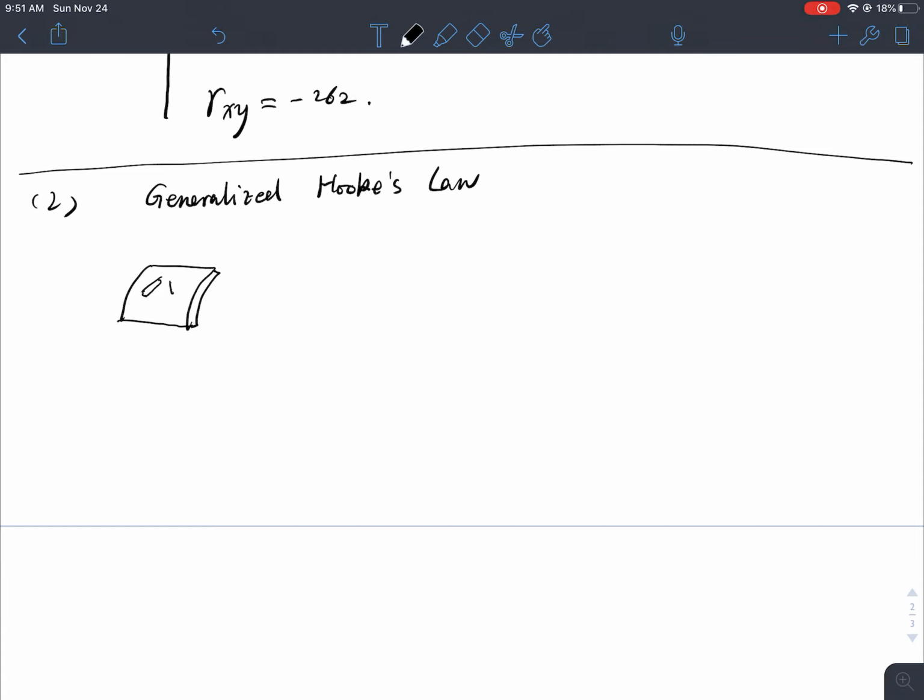And these are strain gauges in a weird fashion. It looks like a cruddy face, but that's what we have, right? So in this pressure vessel here, let's take a look. So we have this stress component, y, or better known as the hoop stress, theta, and then we have a longitudinal stress.